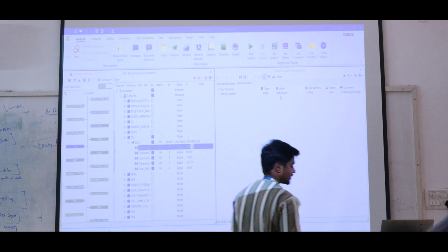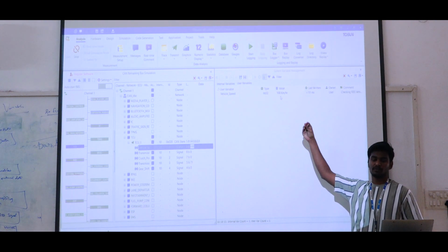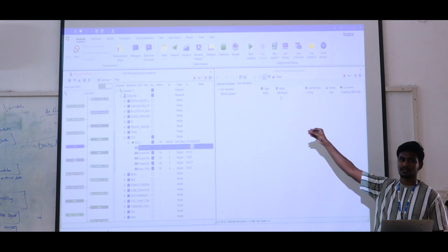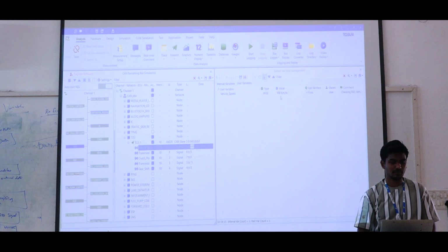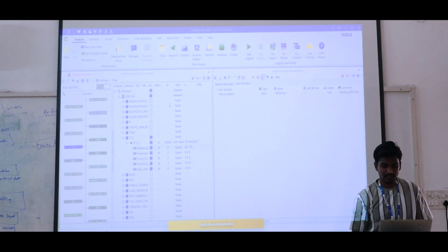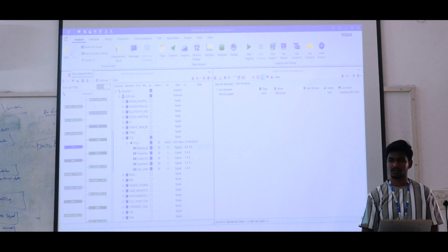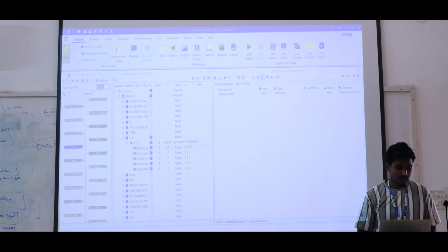Okay, once again I will explain. After proper mapping, which means all the signal and system variables are mapped, next we move to the parallel step. You have to open the CAN database simulation and then the system variable. First you have to start the main simulation. Afterwards you go to the rest of the simulation.